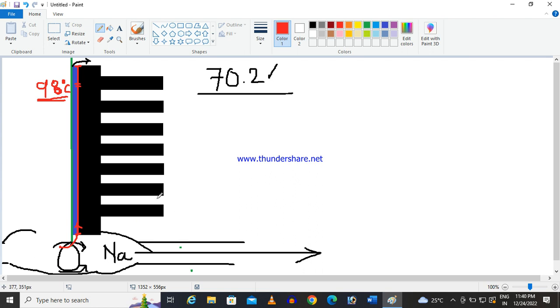that is based on Fourier's law, and convection based on Newton's law of cooling, and radiation based on the Stefan-Boltzmann formula. So emissivity also is a critical factor, but here in my analysis I have neglected the radiation, the heat evacuation through radiation. The major heat transfer through the fin will be contributed by conduction and convection.